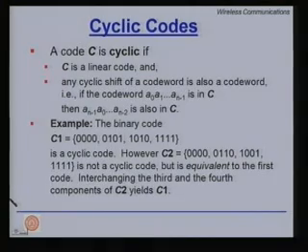Now, we learnt last time that the objective of error control coding is to add redundancies in a known manner, such that there is enough algebraic structure within the code. Whenever there is an error, this structure breaks, and if we are smart enough, we should be able to detect an error and hopefully reconstruct it back. So, that is the whole idea of adding structures.